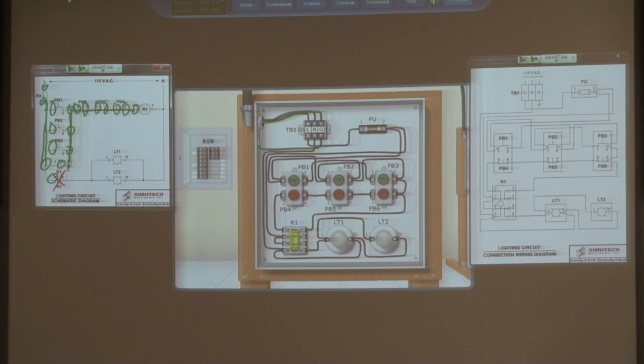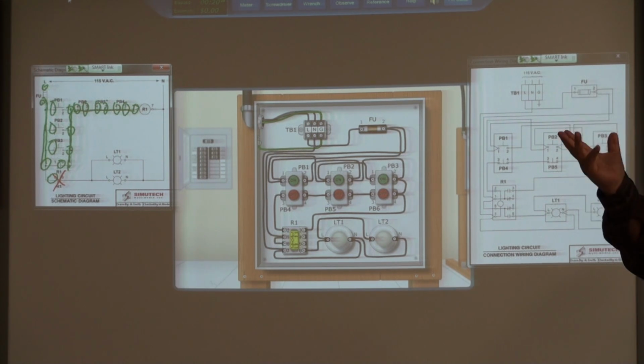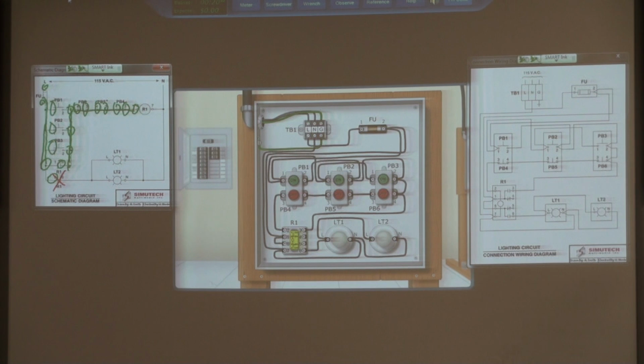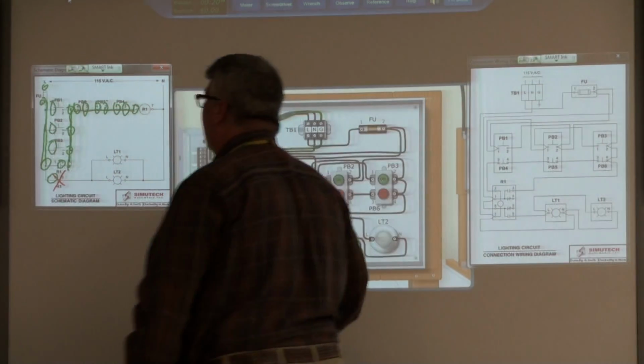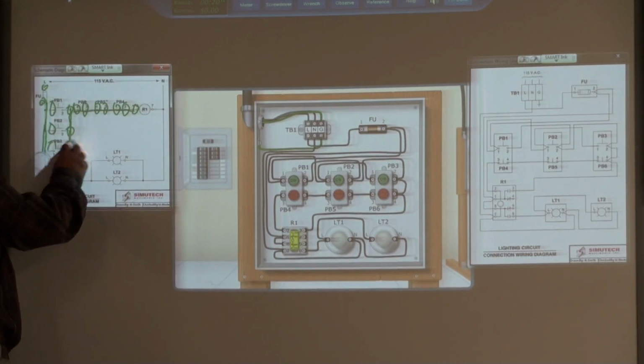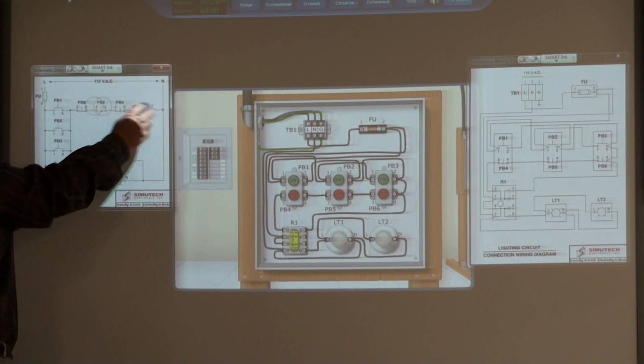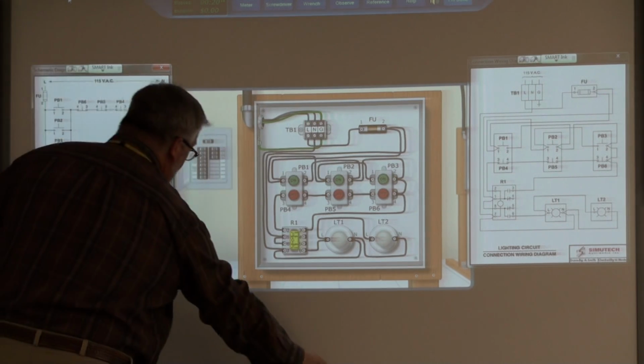If it's welded to that pin 5, then yes, you would read it. But if it's migrating away from the normally closed, but not pulling all the way over to the normally open, it can literally be in between. So yes, maybe, but not definitely. That is a very valid point.